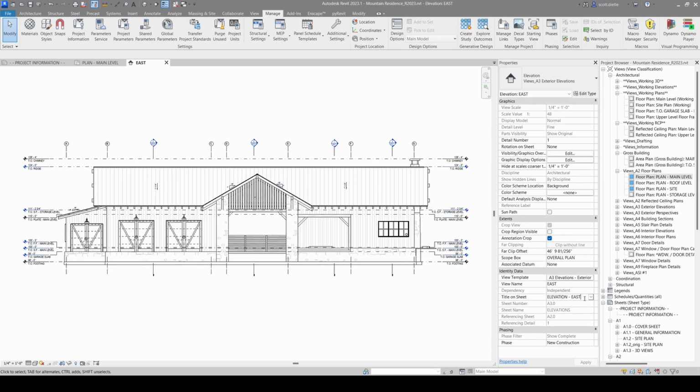We can see that elevation east. So it's not the direction your elevation view is looking at the building. If you were to look through the building and off into the distance, that distance would not be east. It's the direction that your building is looking, technically, from each face, if that makes sense. So it's just an easy way I like to think of it. Sometimes I just think of which direction this face is looking. Oh, it's looking north. It's a north elevation.